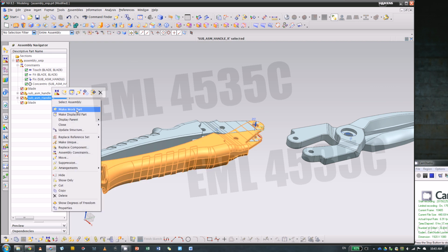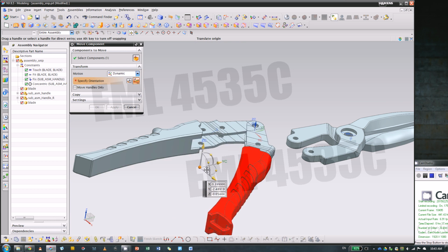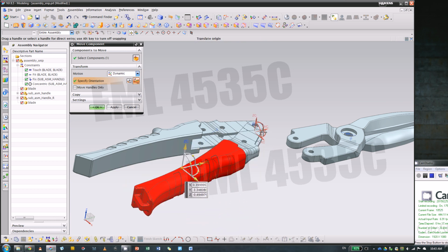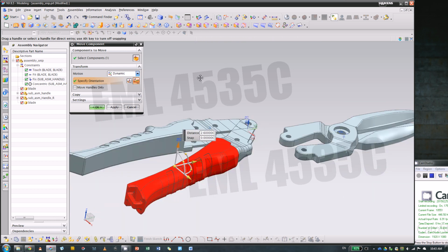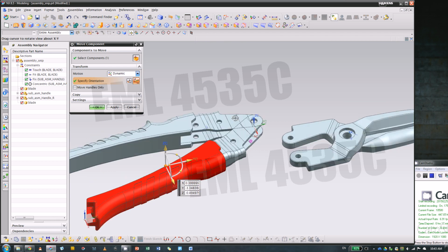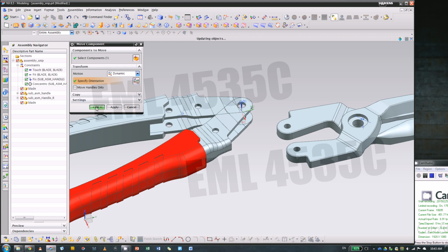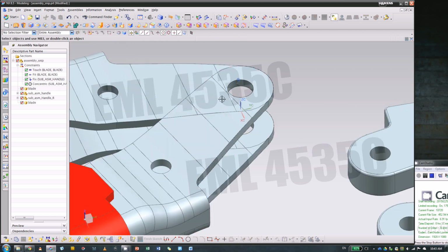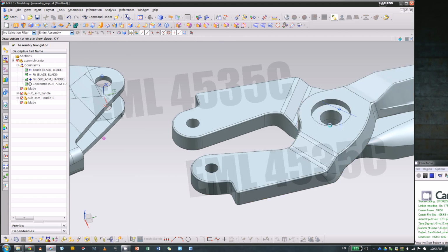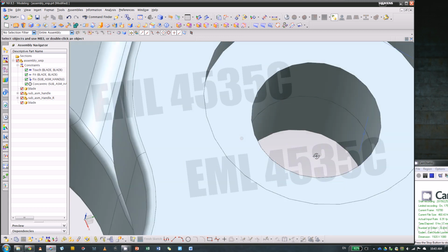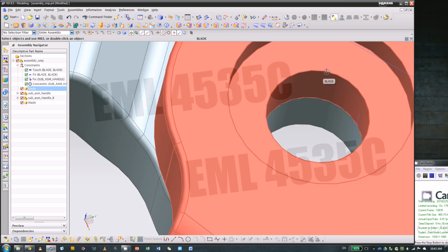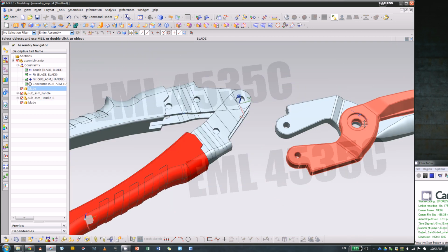So if I right click on the subassembly and move this, you can move, rotate, but you cannot move on axial direction. Nothing happens because it's concentric. It's a constraint that'll put two circles in the same plane and on the same center, of course. Alright, so for this case, you can use concentric sometimes. If you want to use concentric, you have to pick the two circles that are touching each other. If you pick the top and the bottom circles, that'll be a problem.